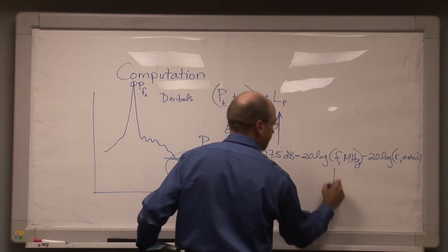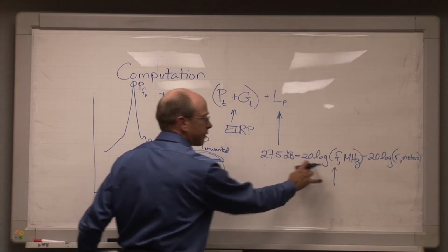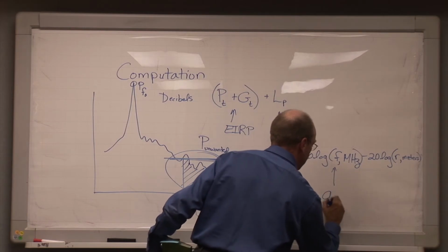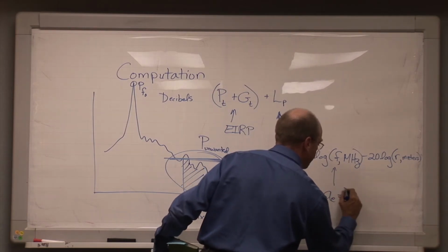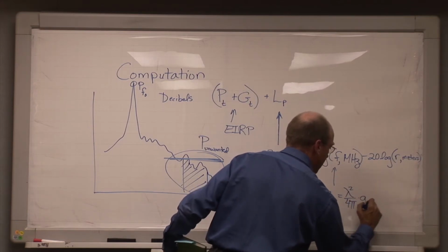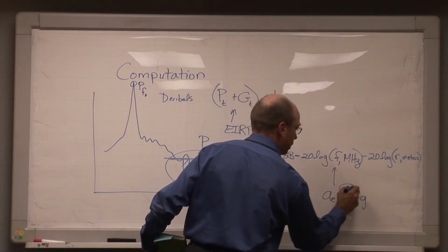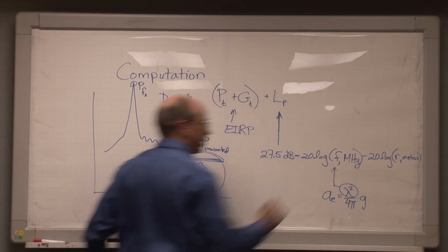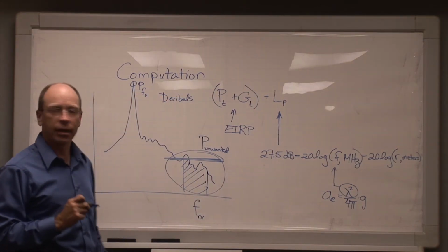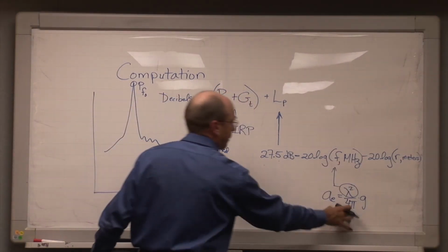And remember that this frequency term has nothing to do with some change in propagation loss as a function of frequency through the atmosphere. This comes from the effective aperture of an isotropic antenna being described as lambda squared over 4 pi times the gain of the antenna in linear terms, and so the lambda squared term becomes a 20 log frequency term when we take lambda as c over the frequency, as the speed of light over the frequency. So this is an artifact of the way that we describe the effective aperture of antennas.